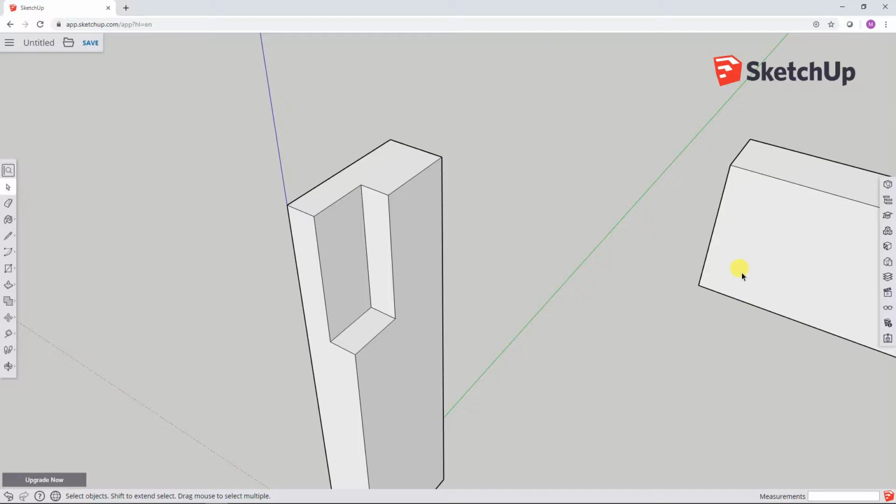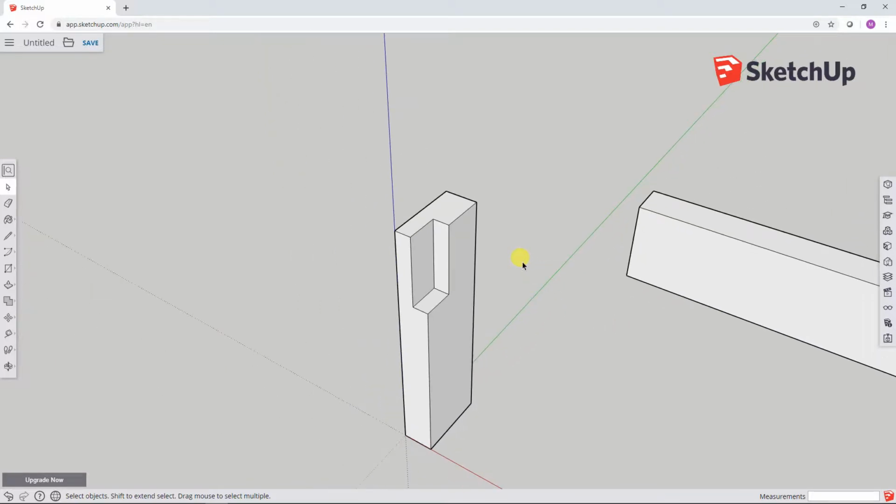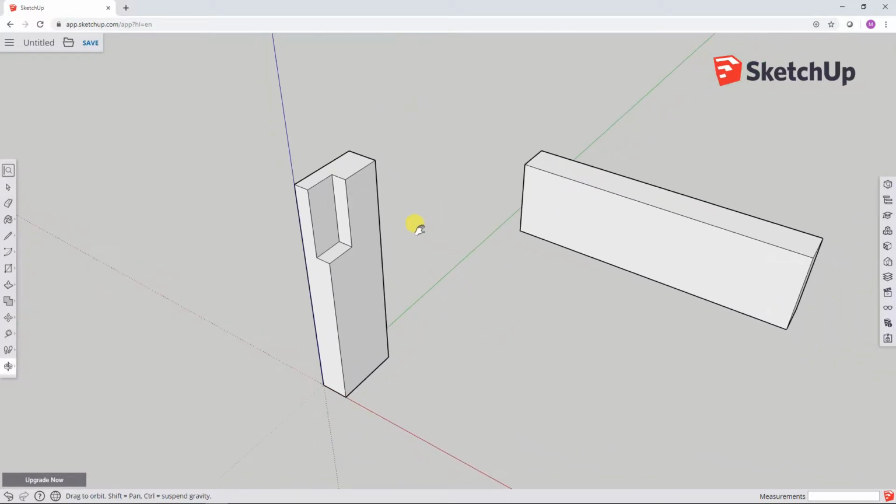So if I zoom out, pan over, and select the move tool, I can take this endpoint. Well, before I do that, it's very important to make this a group again. So I'm going to select the whole thing from left to right, right mouse click, make group.